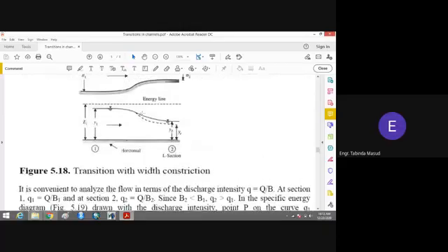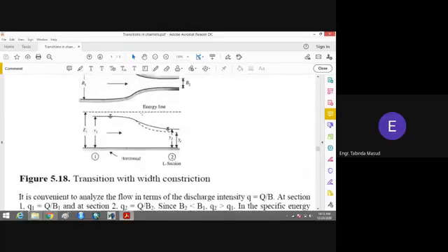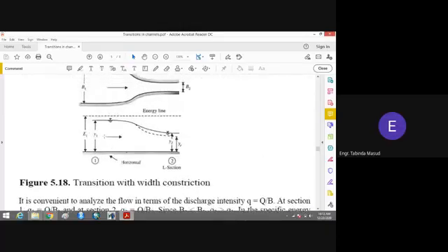That is, what will happen? This y1 will start increasing. yc will not get further reduced, but this y1 will start increasing. The depth of the water will keep increasing. However, when this depth of the flow increases, the value of yc will also change. The depth of the flow will be yc, but its value will be changed. Why will its value change?